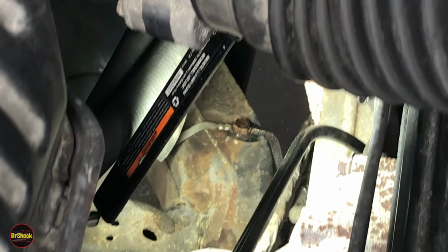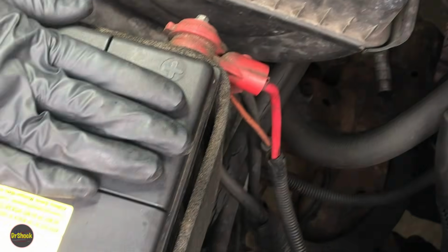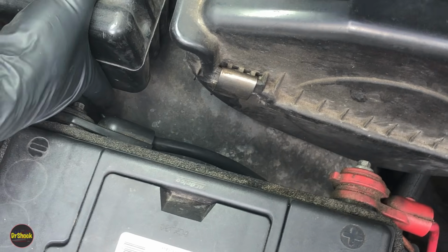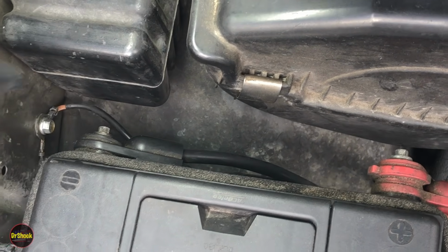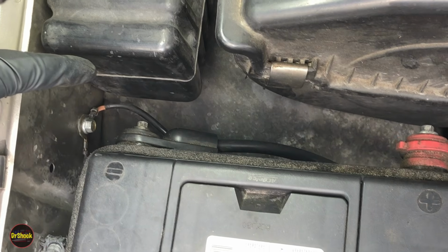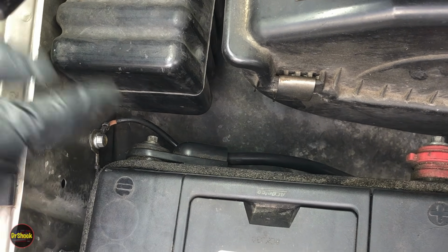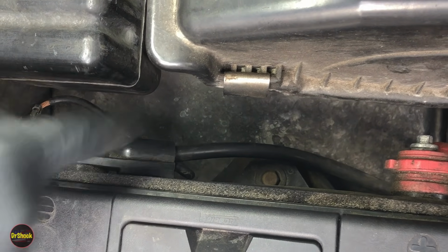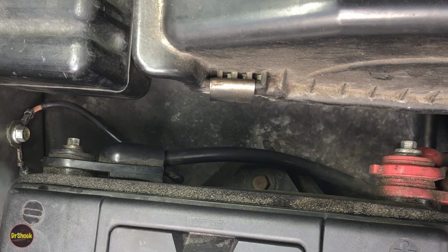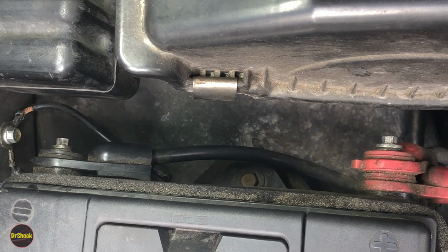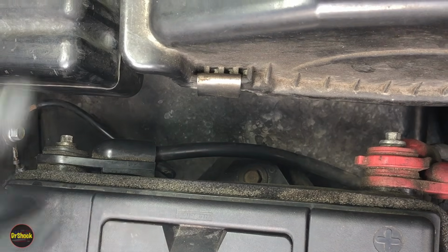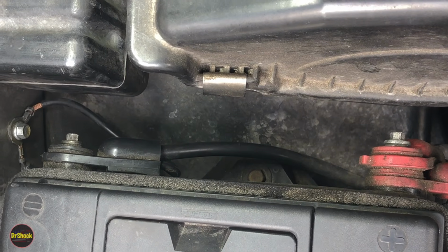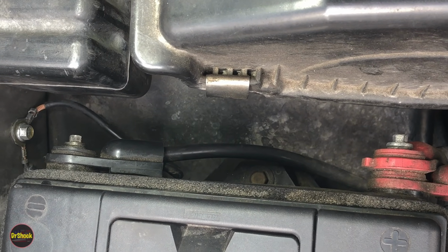If we come back up to the front again, and we talked about G101, we want to make sure, of course, if this cable going to G101 down here is broken, frayed, or exposed, you may end up having to replace this whole negative battery cable to fix that problem. Also, make sure you follow the negative battery cable over and check the stud and nut where it attaches to the engine. All that together would be circuit 150 and part of the diagnostic that you'll need to do to hunt down excessive resistance leading to this diagnostic code.